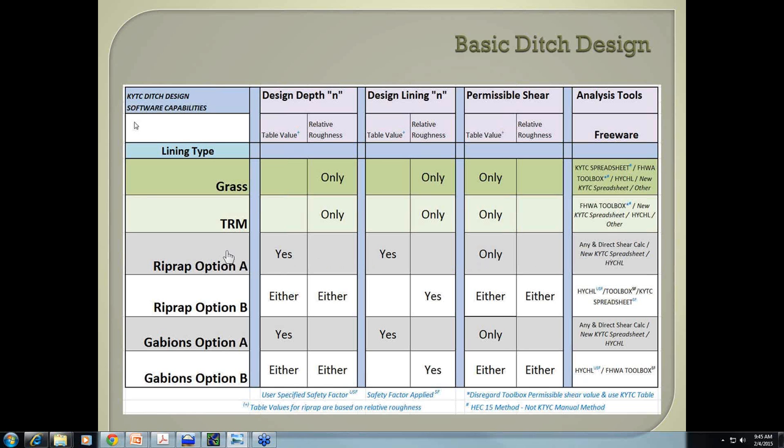This row would apply to less steep slopes, common mild slopes. This option would apply to steeper slope options where you get some benefit from adjustment of the Shields parameter in the model.